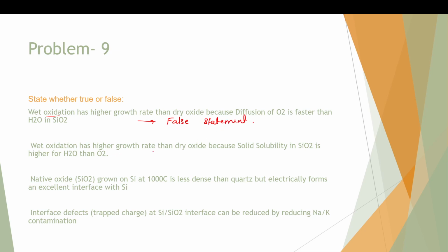Wet oxidation has higher growth rate than dry oxidation, again correct, because solid solubility in SiO2 is higher for H2O than O2. So this is true, as we have already discussed.